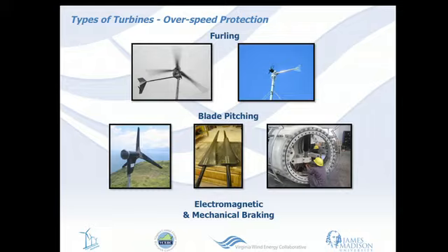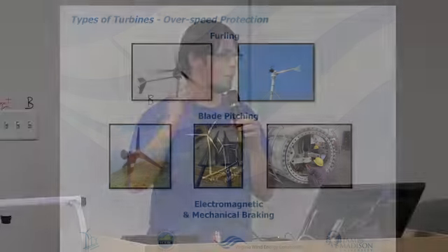The picture in the middle, I don't know if you can see it too well, but in the blade on the right, right here, there are some that are designed where the tip of the blade will be the only part of the system that switches the angle of attack, but it's basically the same principle, trying to break that lift. And in large-scale wind turbines, rather than trying to yaw the whole system out of there, each individual blade has a mechanism with which they can electronically rotate those large blades and shut them down that way, as one of the more efficient ways of shutting them down and keeping them from spinning.